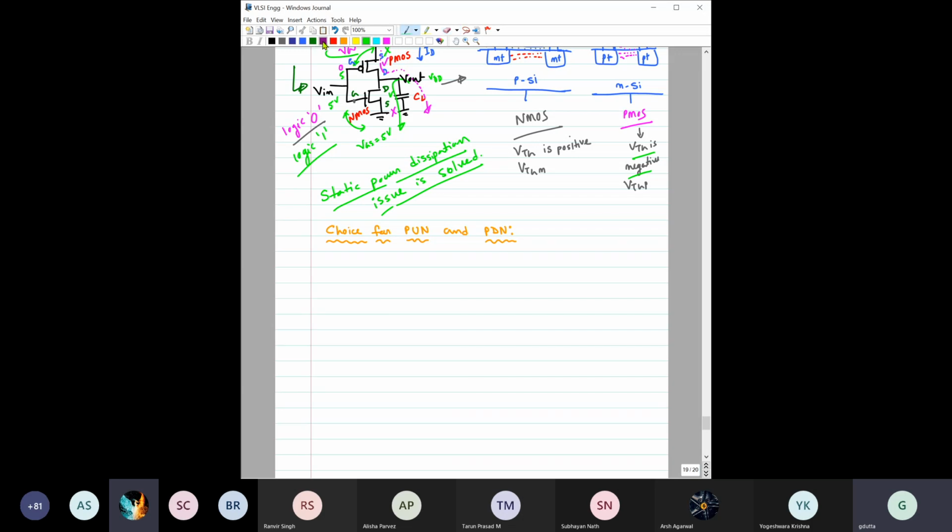Okay, this is interesting. Very good that you thought in that way. Say we are using an NMOS as the pull-up network. So we have used VDD here, and this is the Vin. It is expected we have something below, which as of now we do not know. It is the pull-down network, and maybe it is controlling it, but we do not know what the pull-down network is as of now, right? But we are using NMOS as pull-up.